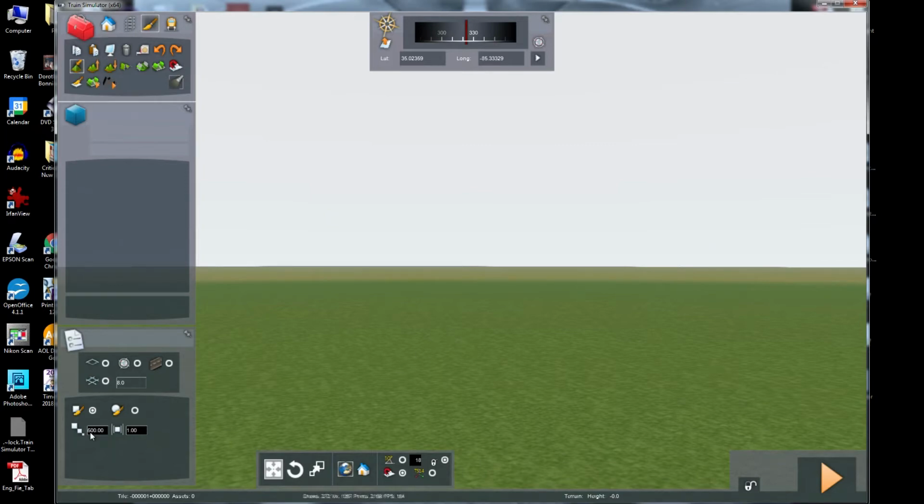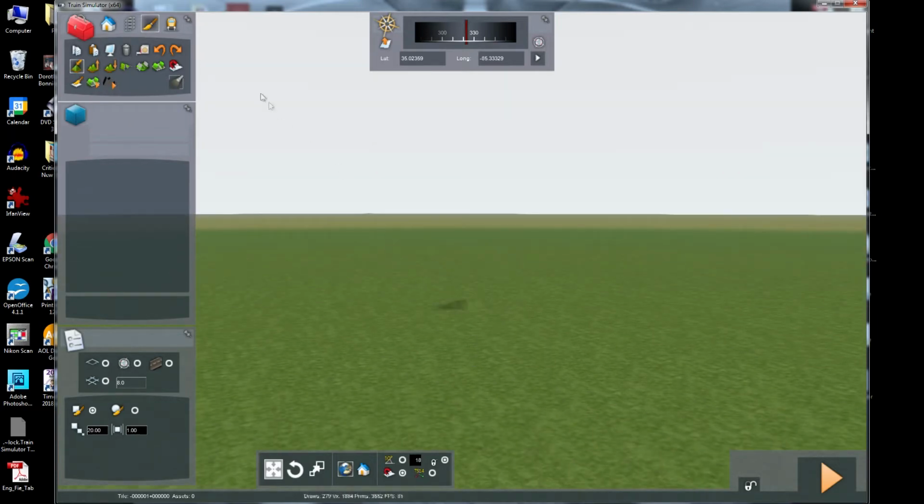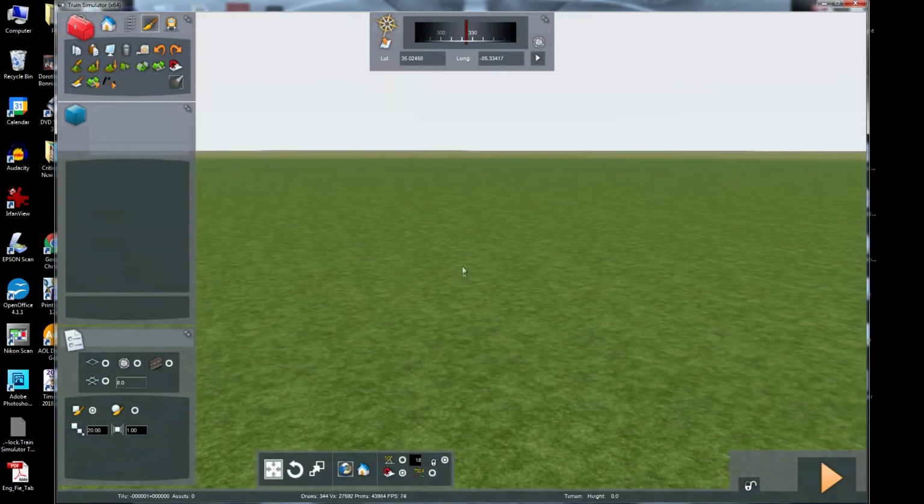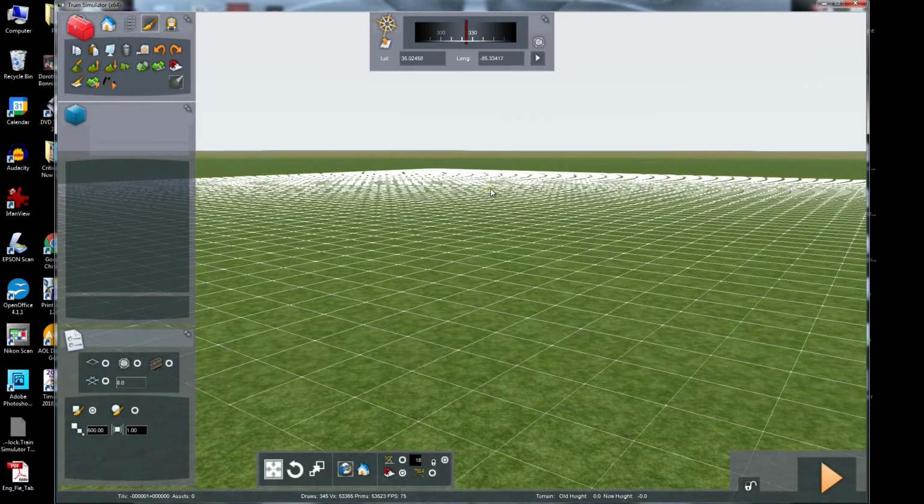If we take height and we set a brush size of 20, when I click on it you see there's the hash marks of the area that it's going to create with 20, and I can pull that and I can make a peak come up. I can make a depression by going the opposite direction. I'm increasing or decreasing the height of the terrain based on the size of the brush, which in this case is 20. If I make that 500, look at the size of my brush now. Oops. That was 50, not 500. So there's the size of my brush is 500.